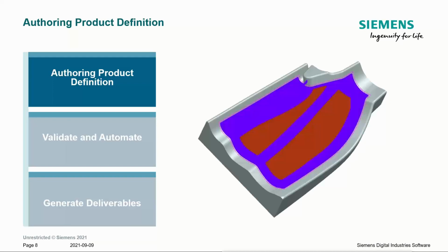So the area you see that's purple now still has only 3, but in these 2 areas we have 5 components where you see the brown. And then finally we have another reinforcing area where we drop another 3 plies right on top of the existing laminate. So in that red area, we're now going to have a total ply thickness of 6 plies. As I mentioned, Fibersim will build the transitions from the 6 ply to 3 ply area automatically, and then allow us to adjust the spacing between them as necessary.